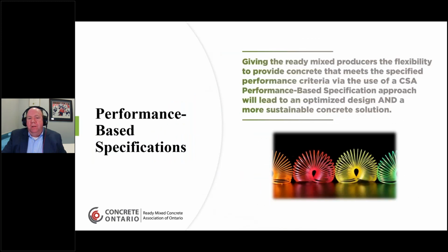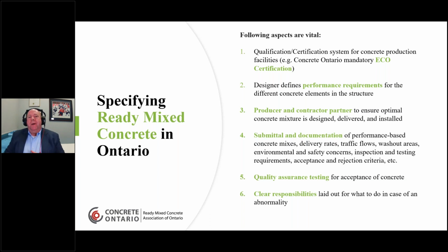So moving along, I'm going to step back, and a lot of these issues relate to all concrete projects. But when it comes to project success, again, first thing is having a very qualified concrete supplier. So again, the association runs a plant certification process, and we certify both trucks and concrete plants to supply concrete. So that's our first step, is using a qualified supplier. Next, the designer has to identify what's their structural or long-term durability performance requirements, what's actually needed of the concrete. So again, they have to spell that out.